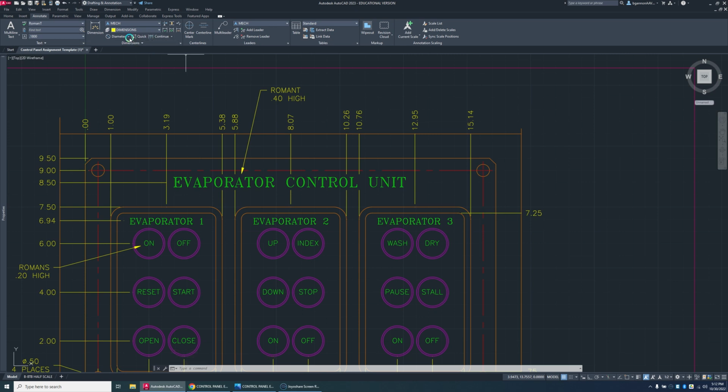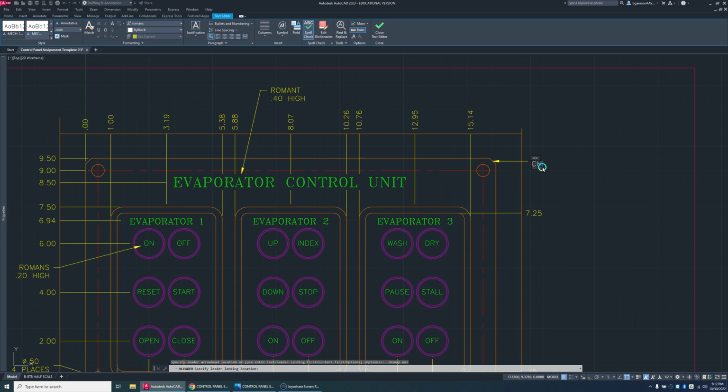Okay, I'm going to add a chamfer. And I hope I can do that one. So I'll do my arrow, multileader. I'll turn my object snaps back on so I can get this point here. I'll do that point, and we'll do perpendicular to this line, just to keep everything in line. I have to move it up in a second. So I'll do chamfer, and 0.25x 45 degrees. We'll have to figure out the degrees, but we'll leave it at 45.